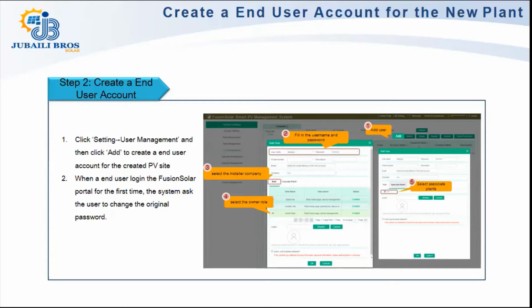You, being an APC, would have multiple plants which you have commissioned using Huawei, but the plant which is dedicated to the owner of that building is the one you would associate. There is a tab next to the role, associate plant. You will click that, go into that particular PV plant, and then edit it for his management and viewing.